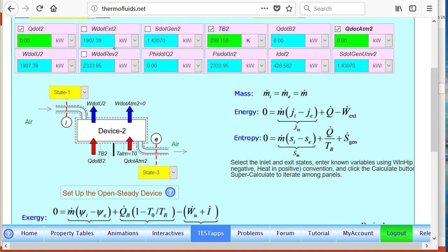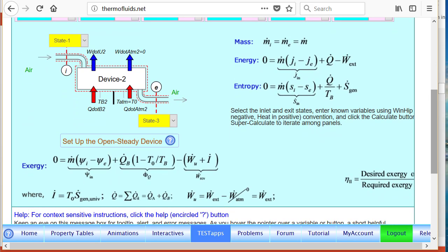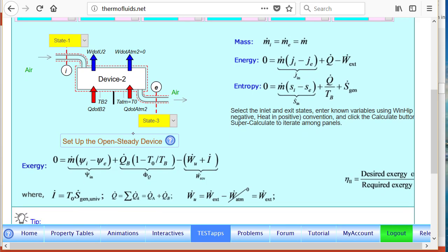The most important one being, for instance, the psi dot. You can see that it calculates the net exergy that goes through the system, and then the reversible work is calculated right from there. And the exergy-related equations are shown here. So this is the reversible work, reversible power, which is calculated from Q dot being 0 here, from essentially the flow of exergy through the turbine.